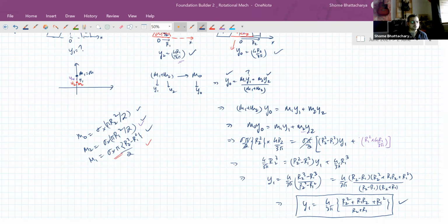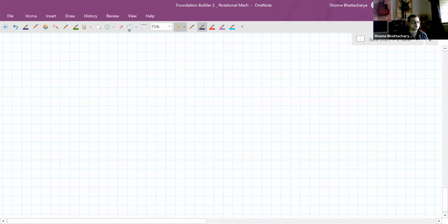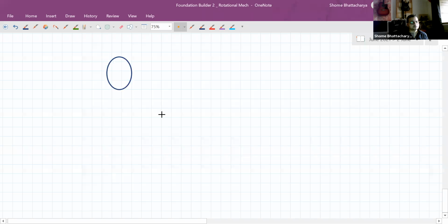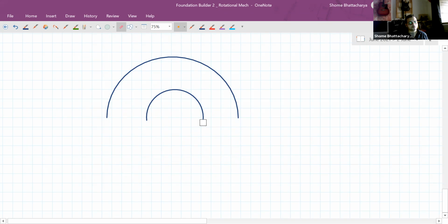Okay, so Deep, hope the question is clear by this method. Yes, sir. Okay, now there is one more method you can apply, which is also not too difficult. It's more like the fundamental derivation method. Just like we've done for the semi-disk, but only the limits of integration will change. So this semi-annular ring, we'll slice it into thin rings and integrate for the thin rings, but with the radius going from R1 to R2 instead of 0 to R.